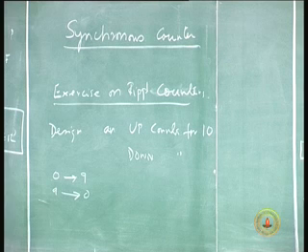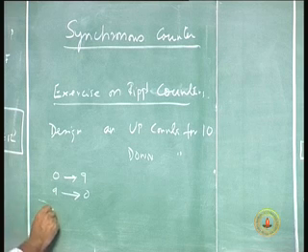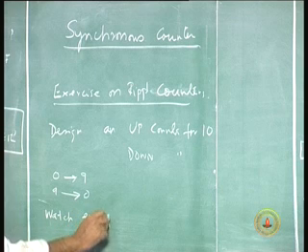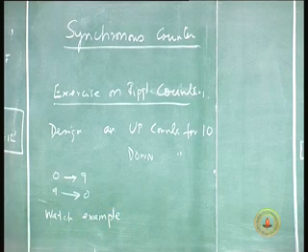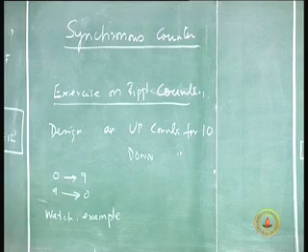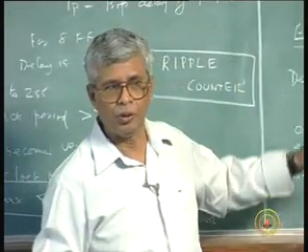We also gave you the clock watch example. These are the assignments on these ripple counters, but actually in a watch we will not use a ripple counter. Finally, because a watch has so many stages, it may not be worthwhile to use a ripple counter, we may have to use a synchronous counter. So, we will talk about synchronous counters in the next lecture.